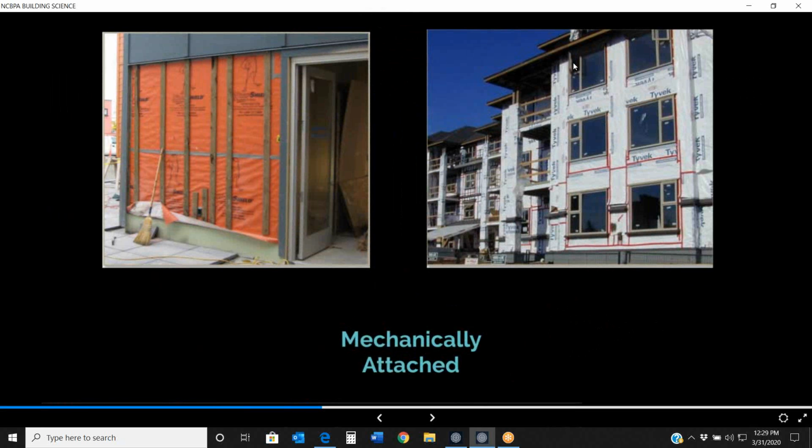And then also moisture. If maybe our substrate's a little moist, it's not going to be too big of an issue here. We'll be able to dry some of that out on the inside, possibly if need be, or it'll dry through if we're vapor open. These come in two different permeance levels. You can get vapor open, vapor closed, and understanding what those are is important. And then understanding how we detail our mechanically attached.